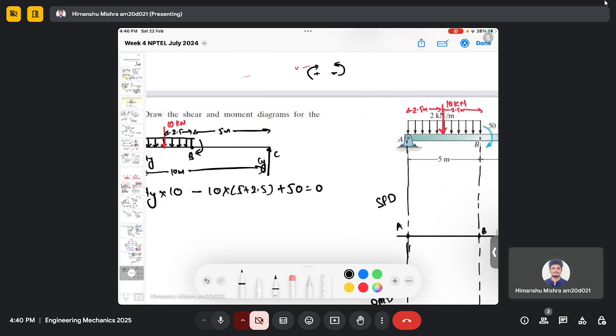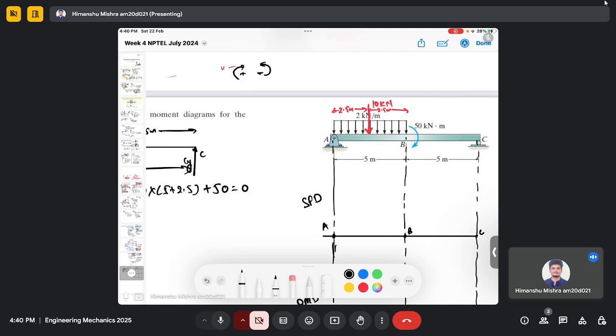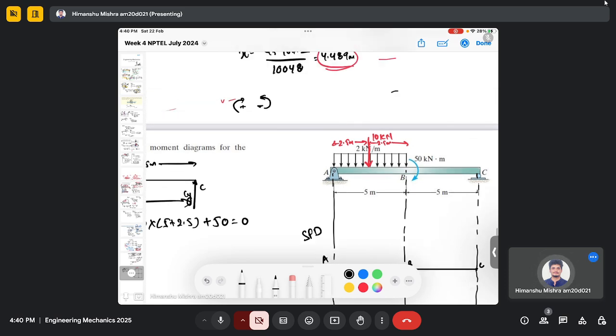Can we call it a couple? I mean, from this diagram we actually cannot, because to call it a couple we also need the direction of force, because a couple is always acting in opposite directions. It is actually because of this opposite force, but here the overall force is zero, but there will be a net moment, and that net moment is actually a couple.